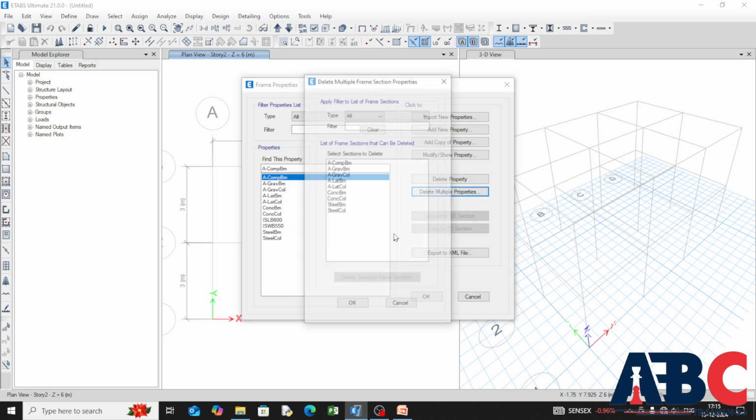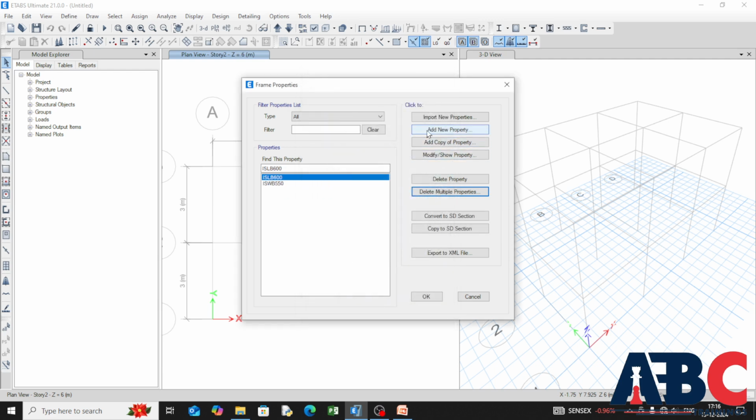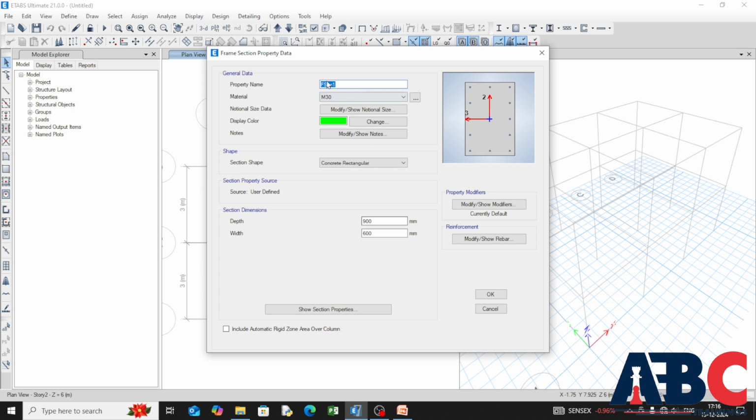As you know from your higher studies, the dimensions of the section have to be greater as compared to normal. So for the concrete column I'm going to give a minimum of 500. The depth is 500 and width is 450, or otherwise it is 400.